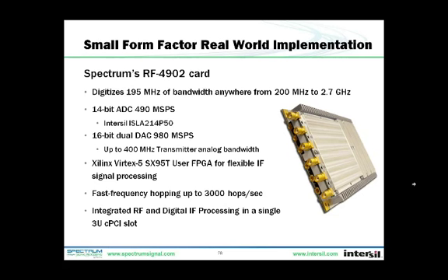It uses a Xilinx Virtex-5 FPGA to do the digital IF processing, and much of the signal processing that would previously have been done in the analog domain is done here in the FPGA. There's enough room here to do digital up and down conversion, along with other processing that's suited to implementation on an FPGA.